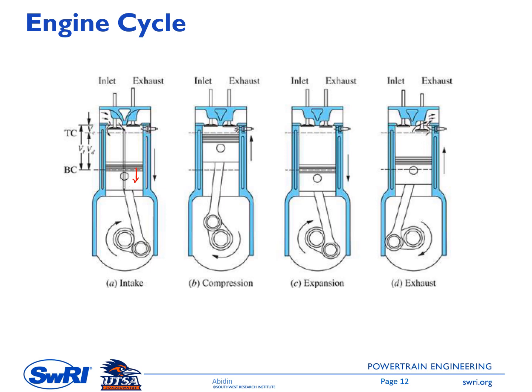So as the manifold pressure, in this intake side, stays nearly the same, then the mixture of air and fuel, or just air, or the mixture of air and exhaust gas enters the chamber as the intake valve opens. So the driver for this inflow is the pressure difference between the intake manifold and the chamber.